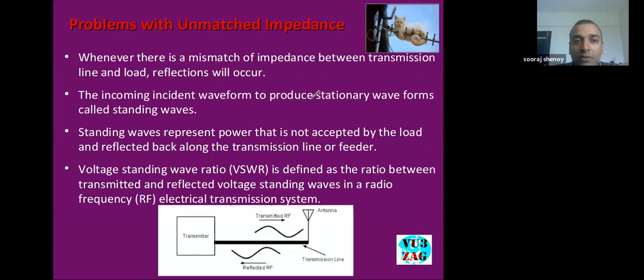Now, what are the problems which arise when the impedance matching is not met? Whenever the impedance is not matched and you transfer a signal to the particular load, then reflections will occur. Also, a lot of losses will occur.